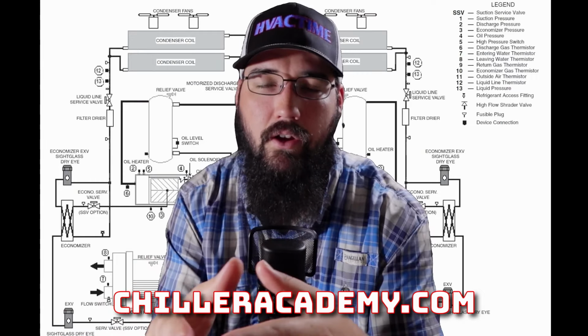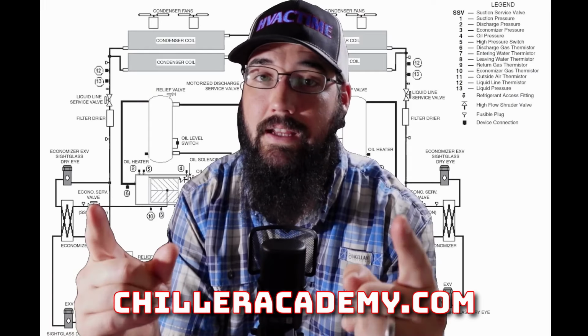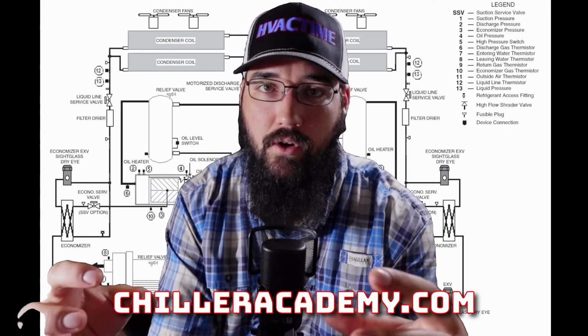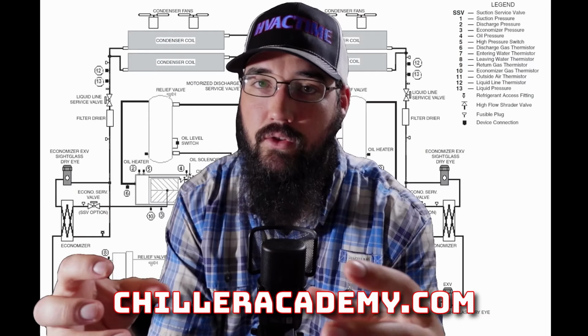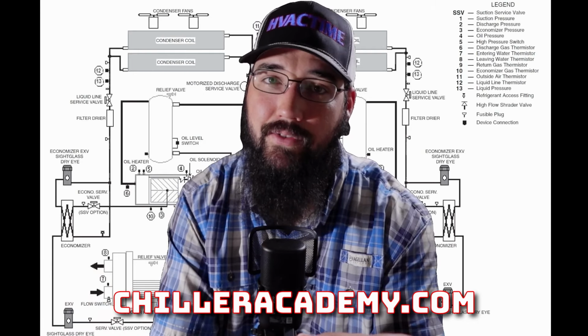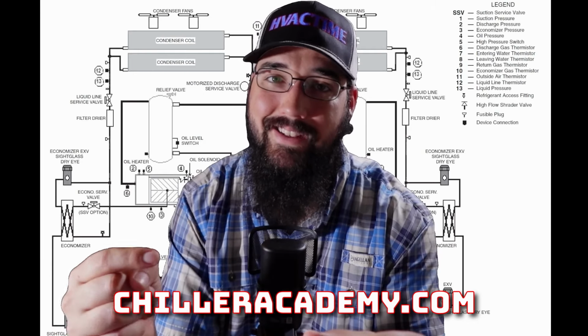So if we have an RLA of 200 amps, we may push that motor to 200 amps, even though our screws are not fully loaded. Just because we hit current limit doesn't mean that there's not more CFM that compressor can technically move.